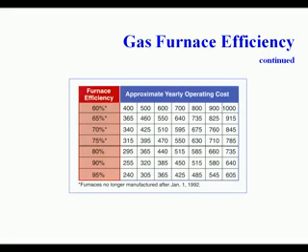Newer furnaces have very high efficiency ratings. These furnaces use less fuel and produce more heat. The measure of efficiency for furnaces is the annual fuel utilization efficiency rating. It compares the yearly or annual energy output to the annual energy input. The higher the AFUE rating, the more efficient and cost-effective the furnace. The federal government's minimum efficiency standard currently is 78% AFUE. Higher efficiency furnaces can have ratings above 84% AFUE.